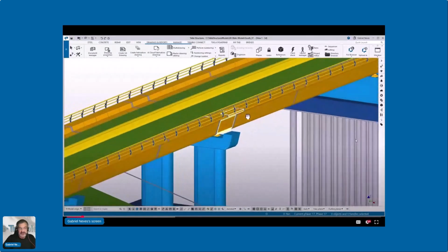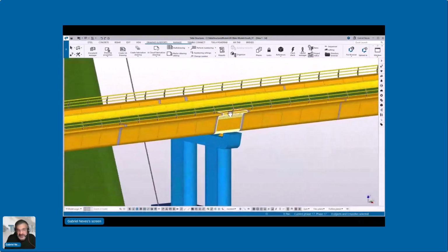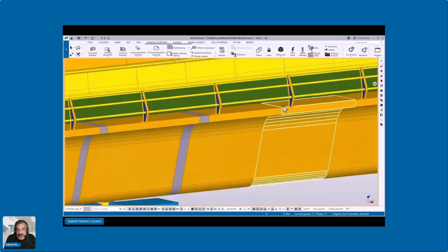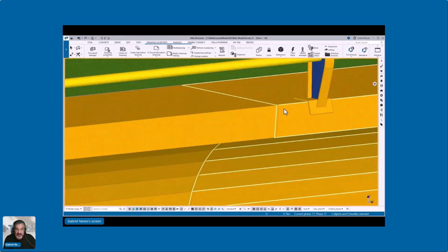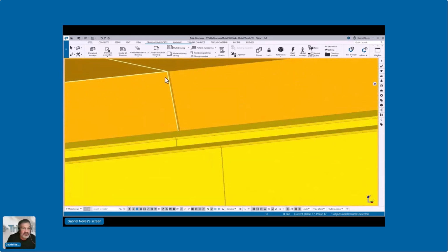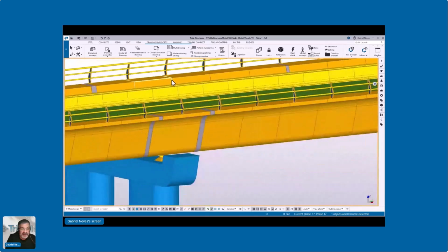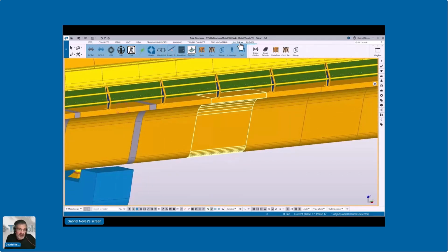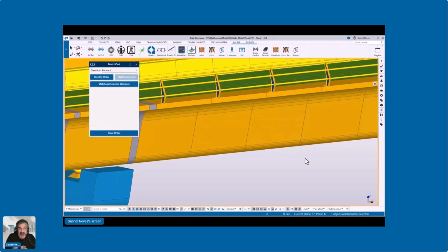Okay, better. So here, Bridge Creator places all these objects, right? And then we have the components. They are quite smart inside Tekla Structures, but you see, because we have a curve, on this side the objects superimpose. On the other side, they are far away from each other. So the extension is just selecting the objects and then saying forward or backward, depending on which side you want to match against the next side or the previous side.